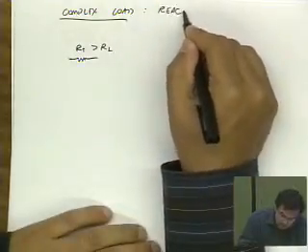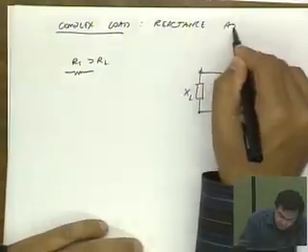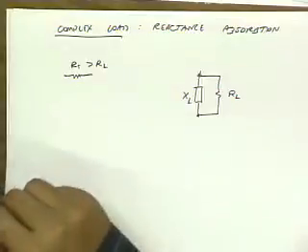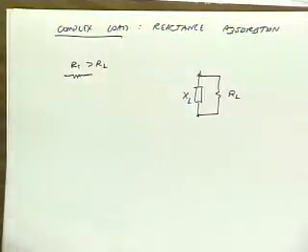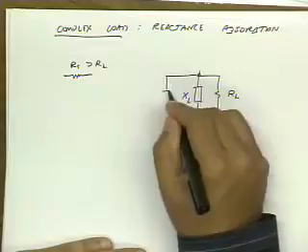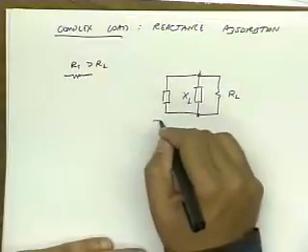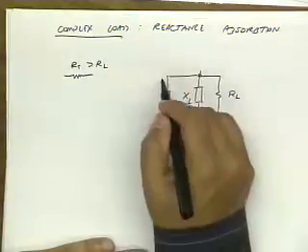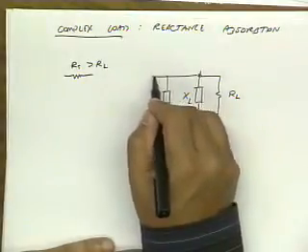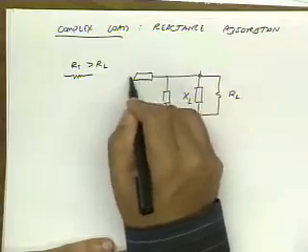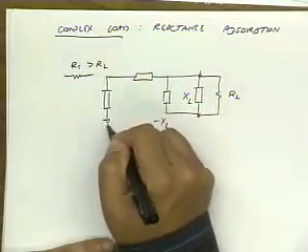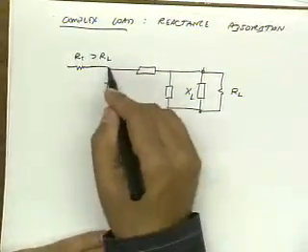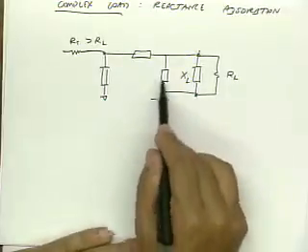I'll give you guys a hint. It's reactance absorption. The idea is very simple. I can just connect minus XL across here. Now I just have RL, and then I just use my regular network. Right? In many cases, I can actually just absorb this into the matching network.